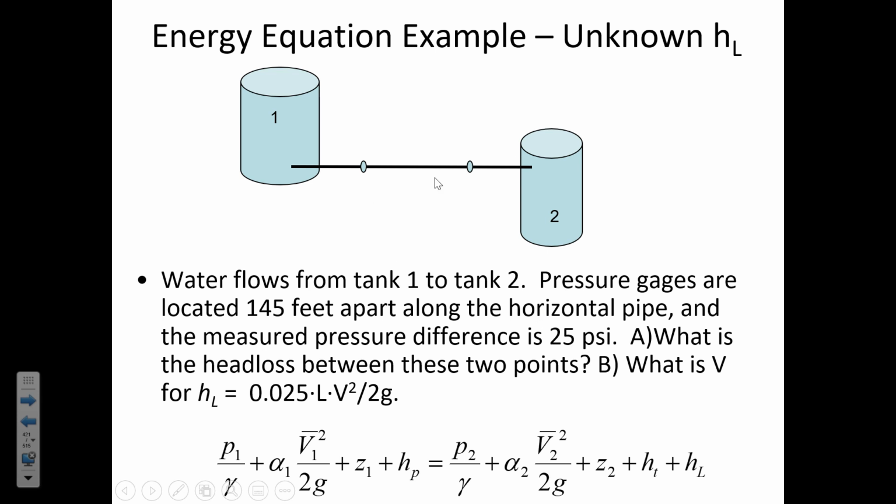The pressure difference isn't caused by a change in velocity. Think about what can cause a pressure difference. It could be the Bernoulli effect, but here it's not, because the pipe diameter is the same, so the velocity isn't different at 1 and 2. It's not because of the elevation difference. The pressure difference occurs only because of pipe friction.